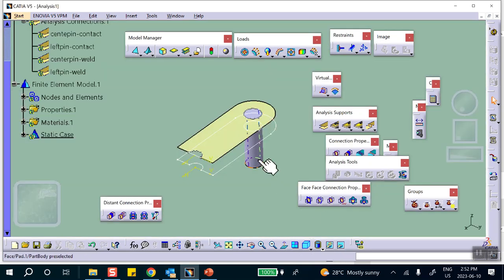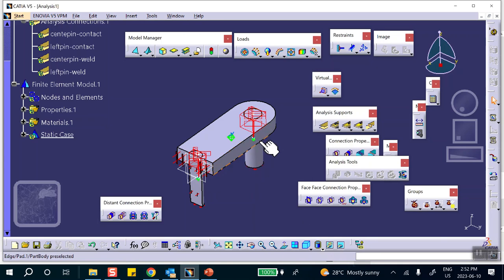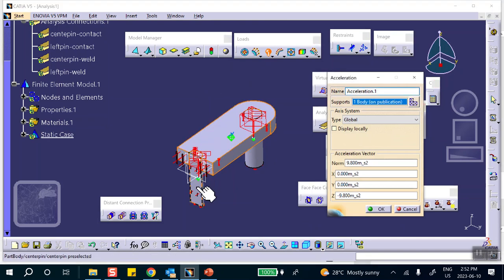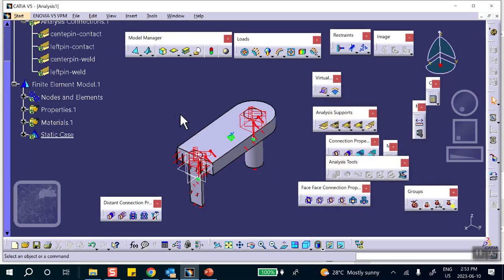Now the entire thing is subject to a gravity loading in the direction shown of 10 G. So we apply gravity to the entire assembly, to this and that, all of them, in the direction Y. Which is that? 600 inch per second squared. 600 inch underscore S2. Please note that I have not changed my units, so they're going to get converted to meter per second squared. But just to show you, oops, wait a minute.